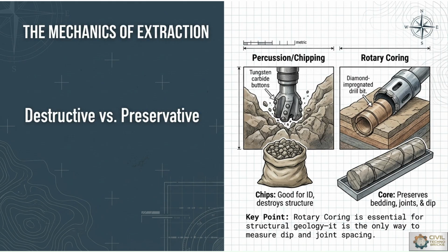Core drilling is a specialized method used to obtain cylindrical rock samples from deep boreholes. These rock cores provide direct evidence regarding lithological characteristics, weathering actions, fractures, and joint conditions beneath the earth's surface. Engineers must evaluate rock quality designation to determine the integrity of rock masses by using rotary coring samples or percussion drilling chips as per their nomenclature.